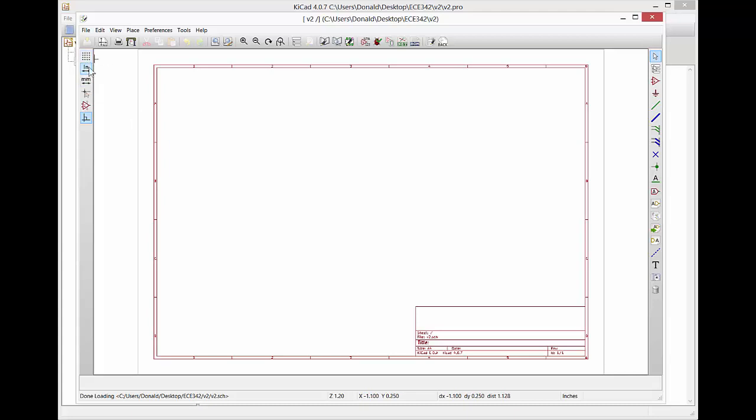But briefly, there's a way to turn the grids on. You can set whether you're in millimeters or inch units. You have the ability to add buses and lines and name nets, add text, etc., add components, which is going to be used a lot in what we're doing here, as well as a variety of things buried in the menus.